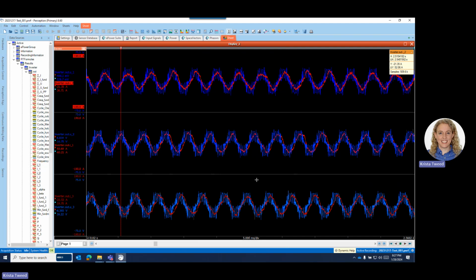So I think what happened here is that there was a wiring issue. And the user, when the power analyzer was wired up, what was actually phase 2 of current was connected to channel I1, and what was phase 1 of current was connected to channel I2. So now, what do we do about this? Because the test engineer would really like to not have to retake the data.